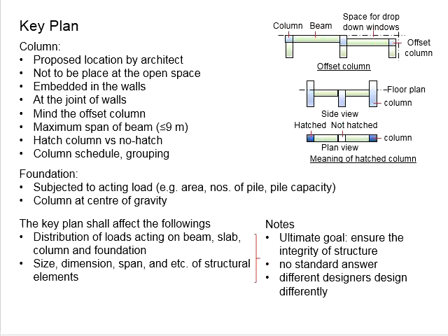Remember, you need to choose an appropriate size of foundation, particularly in terms of the piles. Different sizes of piles have different axial capacities, normally given in tonnage or kilonewtons. This can be acquired from the catalog of the manufacturers.